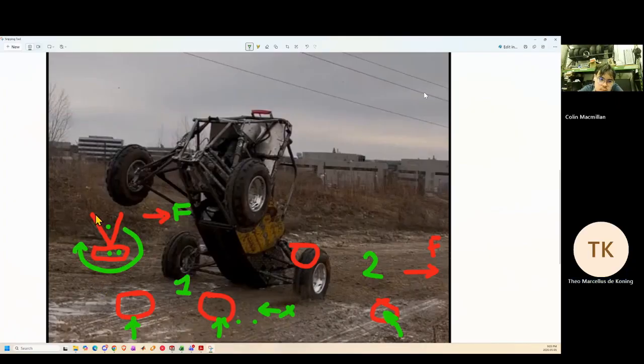which will make this hard point want to go that way, and this hard point want to go that way. Which is not something you guys have calculated for. And so here you might rip out the entire clevis. Versus in case 1, both your forces would just be going in the same direction, either tension or compression.